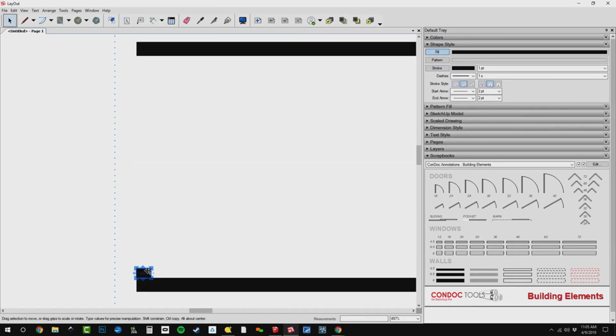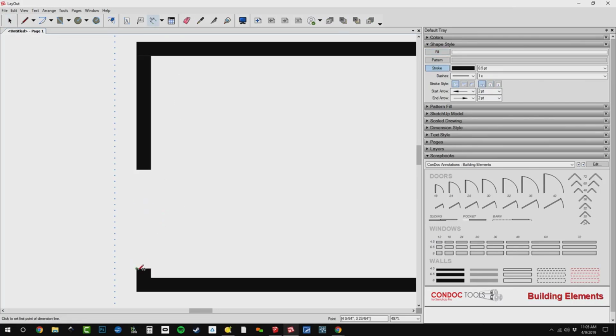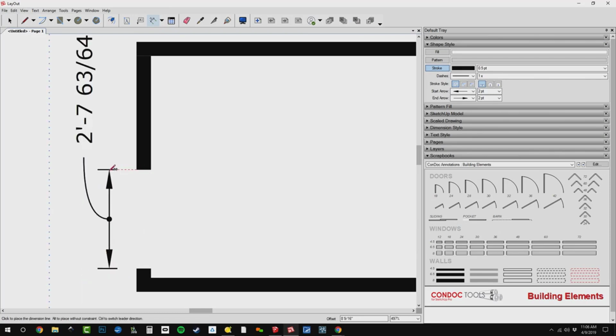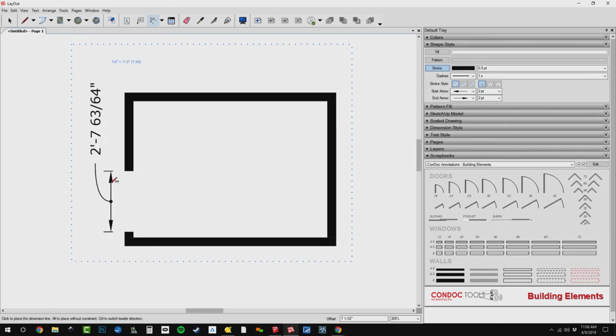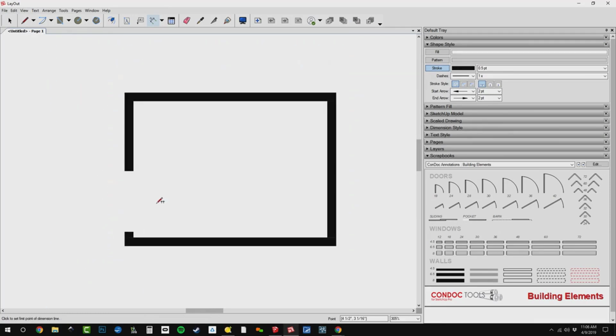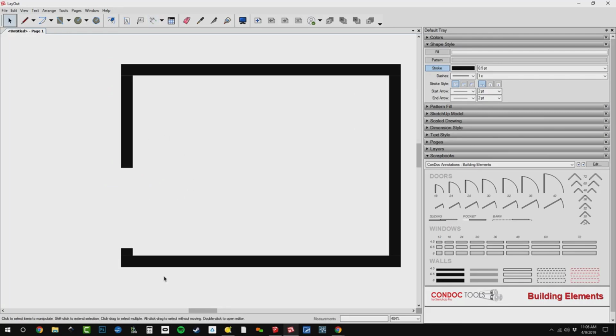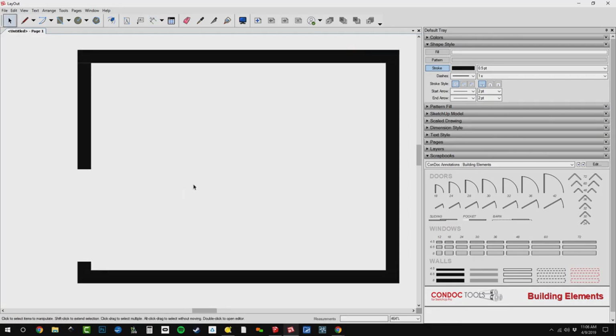So we'll just scoot this up like that, and then stretch it, I'll say 32 inches, enter. And then I can even invert it like that. So now let's try that again, and then we'll move on. So go like this. So you can see my tolerances are just a little heavy, so we're coming in one short. All right, we'll leave that alone for now. So there's my 32-inch opening.